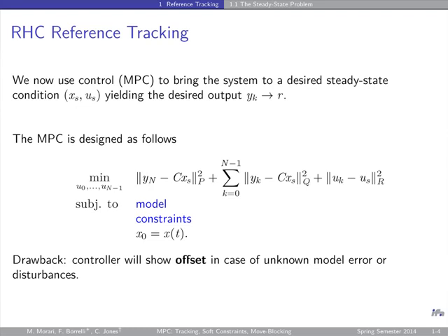This is the MPC problem we'll then solve after we determine the targets. And so you see the changes from before. What are the changes? We didn't have a CXS here, we didn't have a CXS here, and we didn't have a US here. So now we don't penalize the U's, but we penalize the deviations of U from the target, the deviation of Y from the target here and here. And obviously we have the same problem, same model, same constraints, same initial condition, etc.